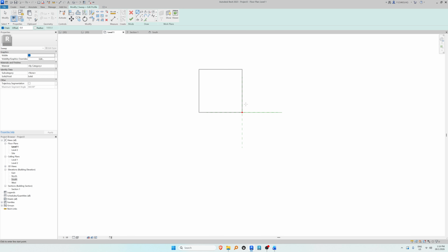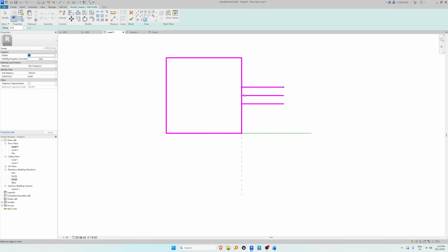Okay, so you understand what is happening. I will find the midway here. Right, so the midway. Next, I'm going to just draw this, a round shape. Pick line. We will offset 20. So one here and one here. I will delete the middle one. Drag this here and this one here. Drag this all the way to 20. Same for this.